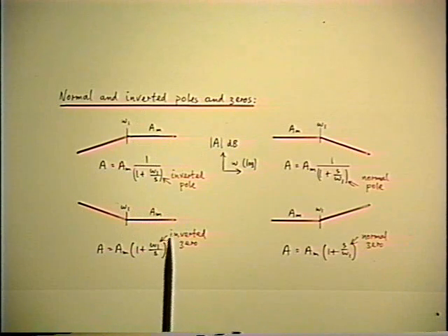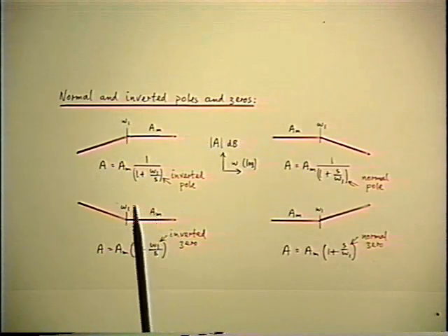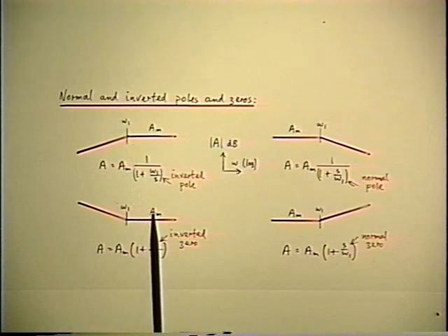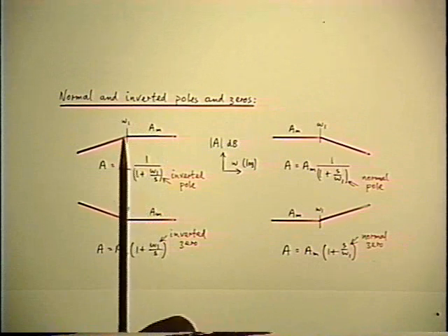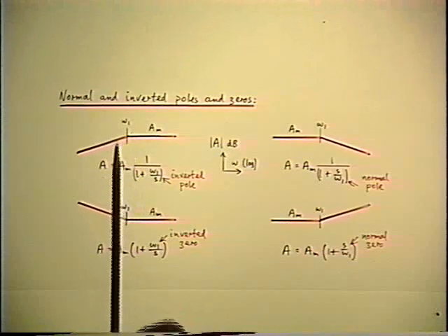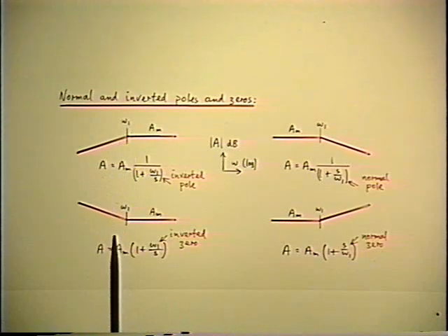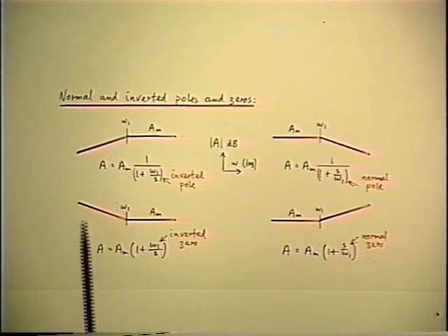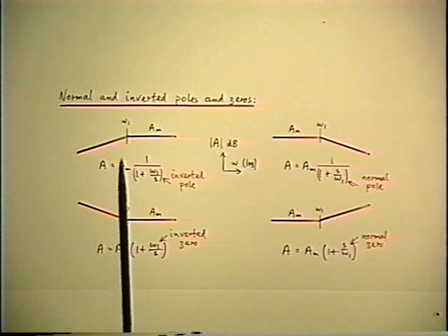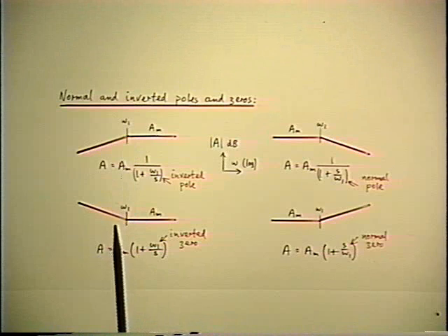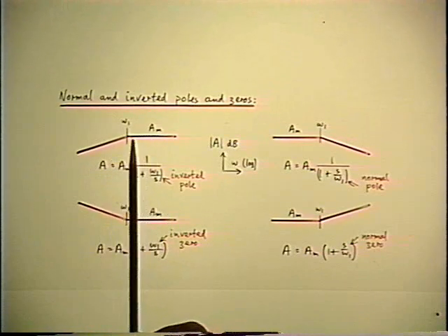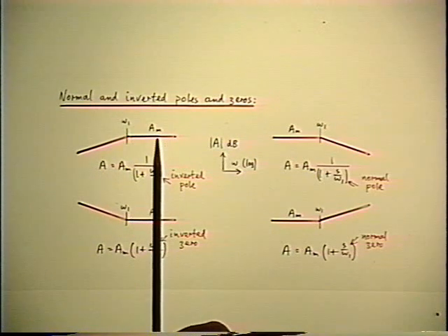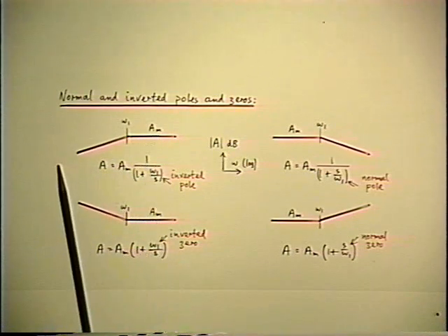And certainly if you're talking about audio amplifiers, usually they are AC coupled. And so the specification is to do with the mid-band gain, and then you have coupling and bypass capacitors that are going to cause the gain to differ from that as you go towards lower frequencies. But the important thing is, where does that begin to happen as you go down in frequency? So the important part of the specification is the high frequency part of the diagram, not the low frequency part.